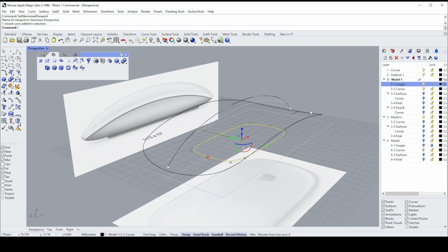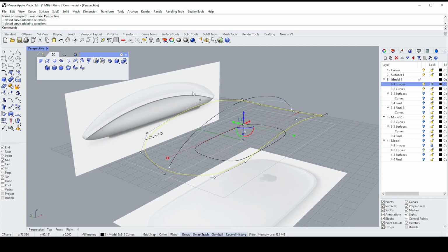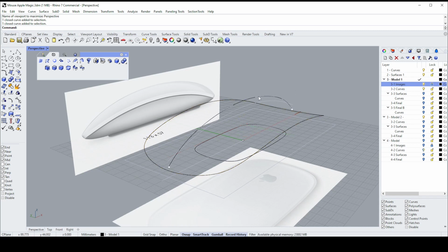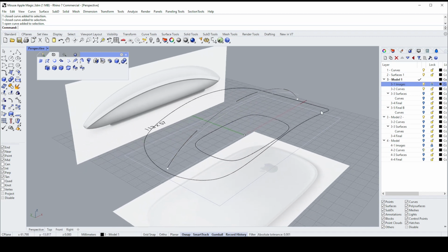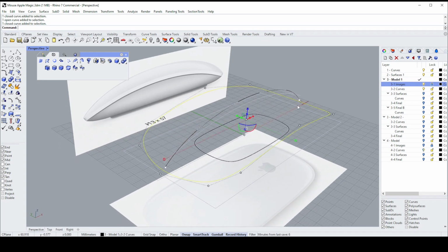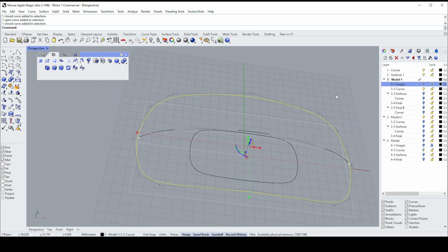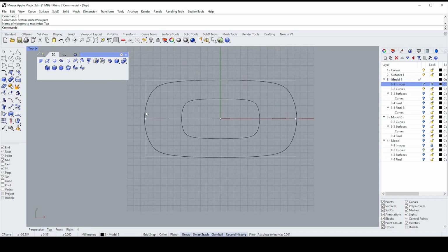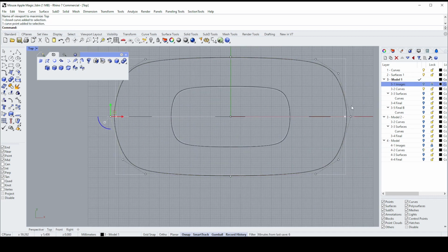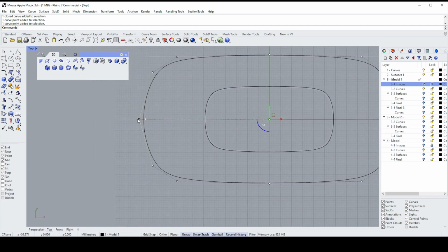There's the base. That'll be the midline, in other words, the sharp line that divides the top surface from the lower surfaces. And then that'll be obviously the limits of this upper surface. So what I want to do now is chop, or split, this curve into 3 parts. So I'm going to switch the images off for now because we don't need them and they get in the way. And go to the top view, and then I will see if I can adjust this a little bit. Not quite happy with that shape. There we go, something like that.